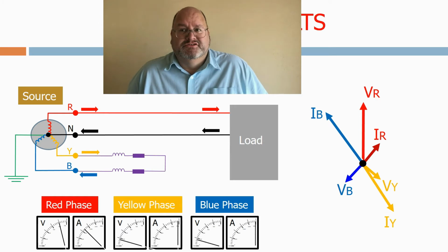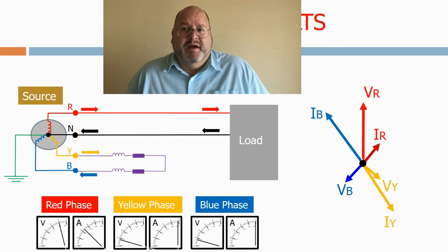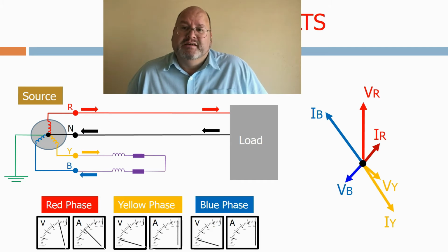The voltages and currents on the healthy red phase are likely to be substantially affected, as we are disconnecting the power on 2 of the 3 phases. Here we have shown the red phase voltage increasing slightly, and the current staying the same, but the actual effects will depend on the load impedances and load types.